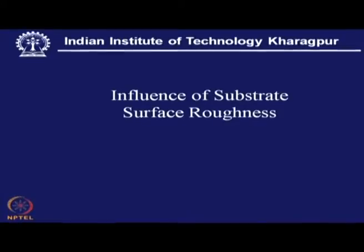Now, influence of substrate surface roughness. When we give importance to this measurement or assessment of roughness of the coating, we find that roughness of the substrate is equally important, particularly considering one particular coating process. Say for example, if it is a PVD coating for a particular material, we like to have one kind of surface roughness. If it is a CVD coating, that requirement may be a little liberal and we need not hold that tight tolerance on this surface roughness requirement.